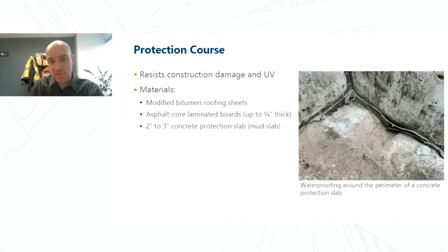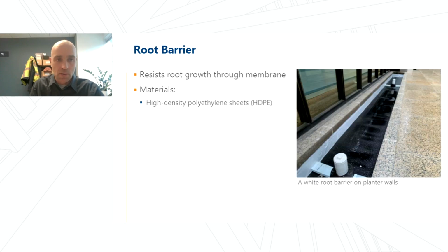It's best practice to install the protection layer as soon as possible after the waterproofing is complete to protect it from the rest of the construction going on. However, it's got to be coordinated with any flood testing or electronic scanning of the membrane. Root barriers.